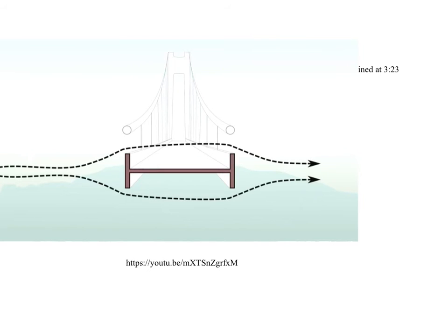You can see in the historical footage that right before failure, the bridge isn't oscillating vertically, but in a twisting or torsional motion. The reason for this change in oscillation is still debated, but one of the best suggestions has to do with the aerodynamics of the bridge. Rather than a truss through which wind can flow, the shape of the Tacoma Narrows Bridge, with the large steel plates on either side, created some strange interactions with the wind.